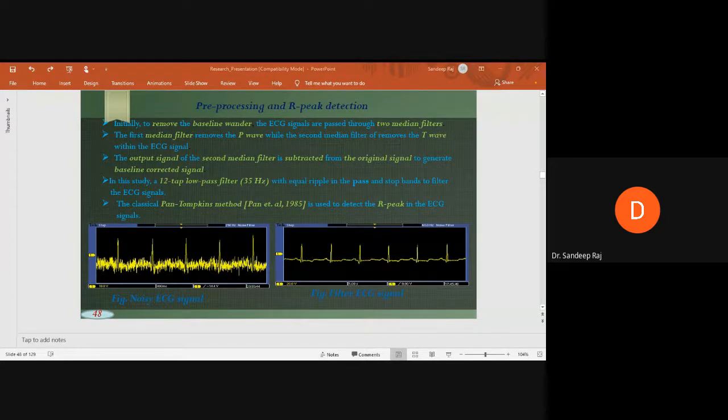So an ECG signal of length n is passed through the n-point FFT stage, and we have received the FFT coefficients as F1, F2 to Fn. Then they have been partitioned into the subbands. Beta-point inverse FFTs are being applied, and consequently we have calculated the features using the DOST method, and we implemented the SVM technique for the classification of these features, and finally we again implemented this method into the hardware